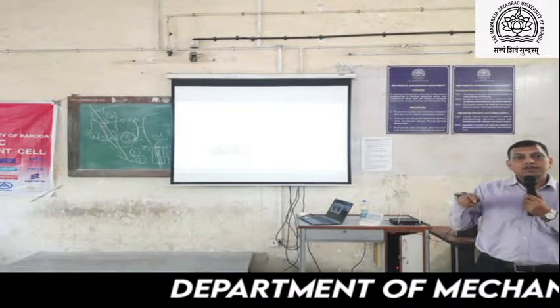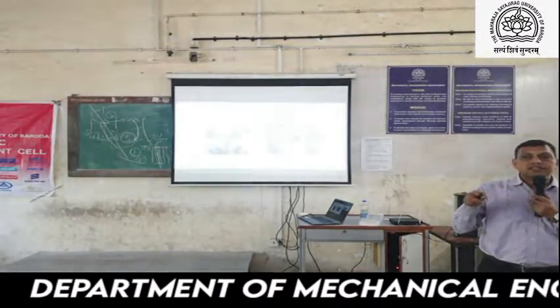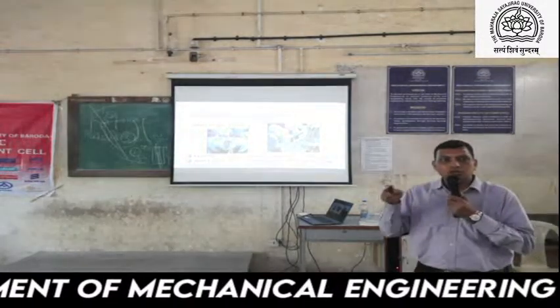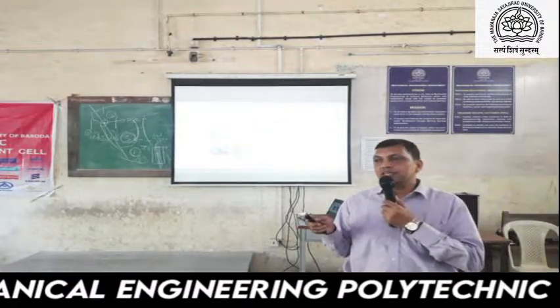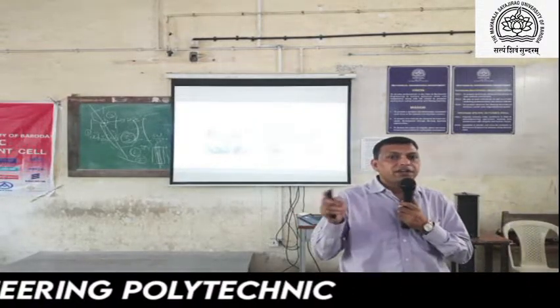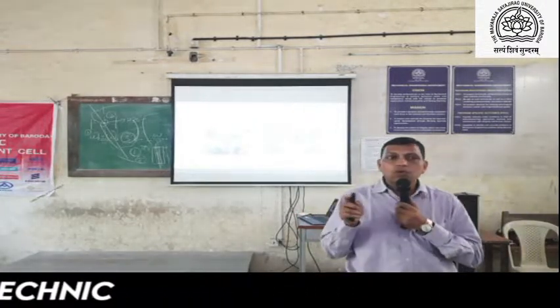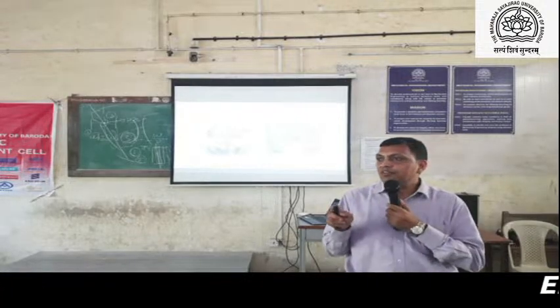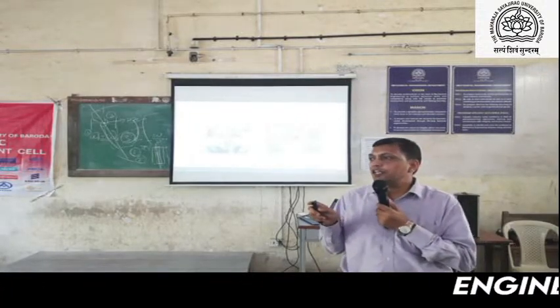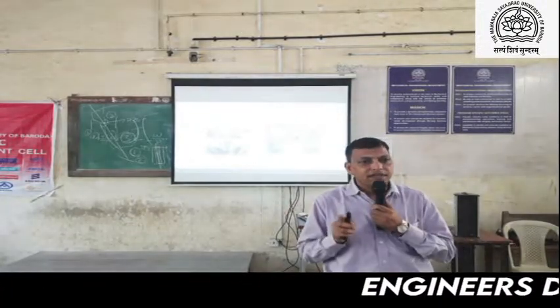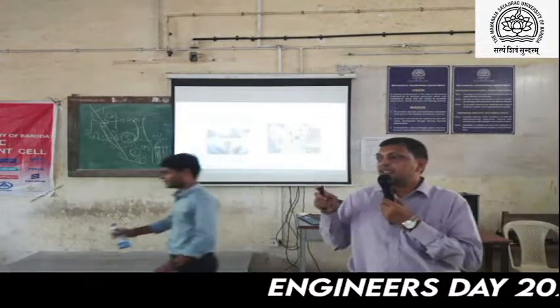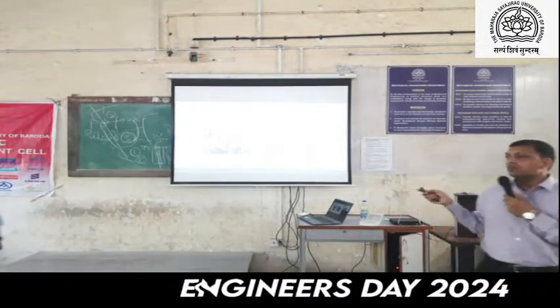During heat treatment, we have already considered some allowances. If the tooth thickness is 8 mm, then during machining we have to consider a tooth thickness of 8.6 or 8.8. That can be finalized at the time of the grinding operation.